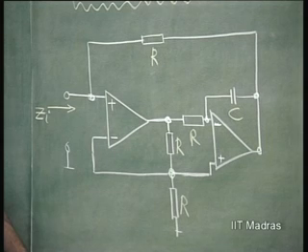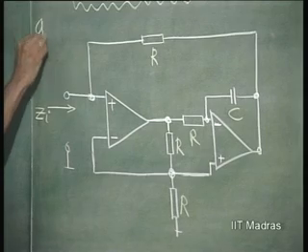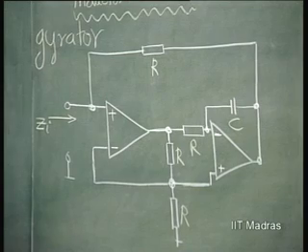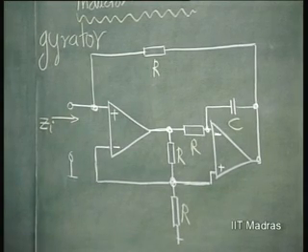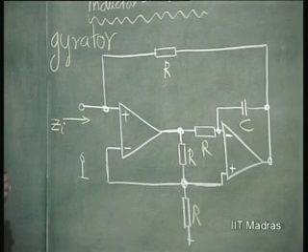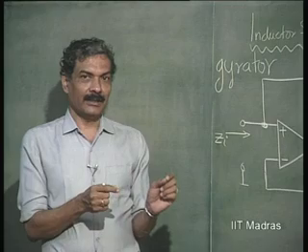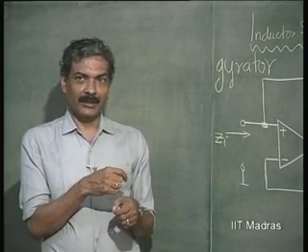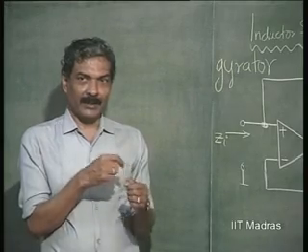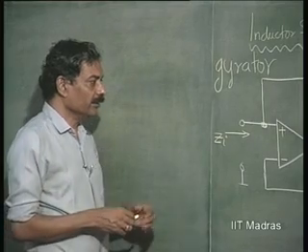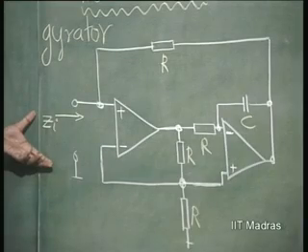How is it possible? Now, this circuit which is called a gyrator. Gyration means rotation, right. What it means is a capacitor has a certain relationship with voltage and current, and that relationship is made use of in order to change this voltage to current relationship for the simulated component, that is the inductor. So, Zi here should become inductive.